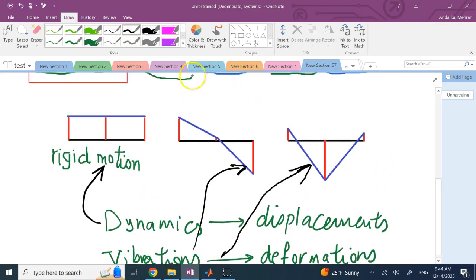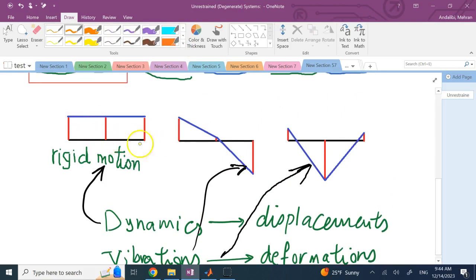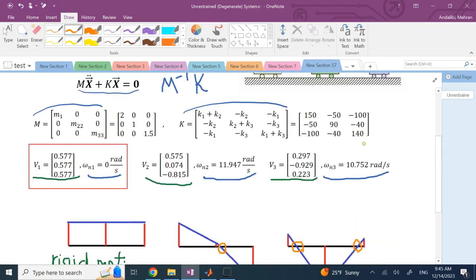And another interesting thing, it's not related to the topic of this video, but you can see the first mode shape has one node. There is one place here with 0 displacement. The second mode shape has 2 nodes. So as the mode shapes progress and you get higher mode shapes, you get more and more nodes, as I showed you with the string example in one of my previous videos.